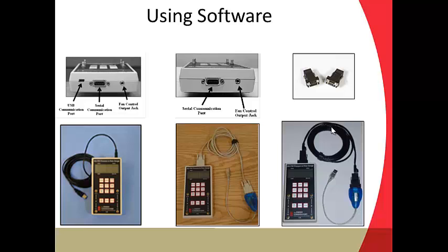But it's hard to roll up, and it's more fragile. You're more likely to break those single conductor cables. So stranded is a better alternative, easier to roll up, and more durable if you're using it for this purpose.